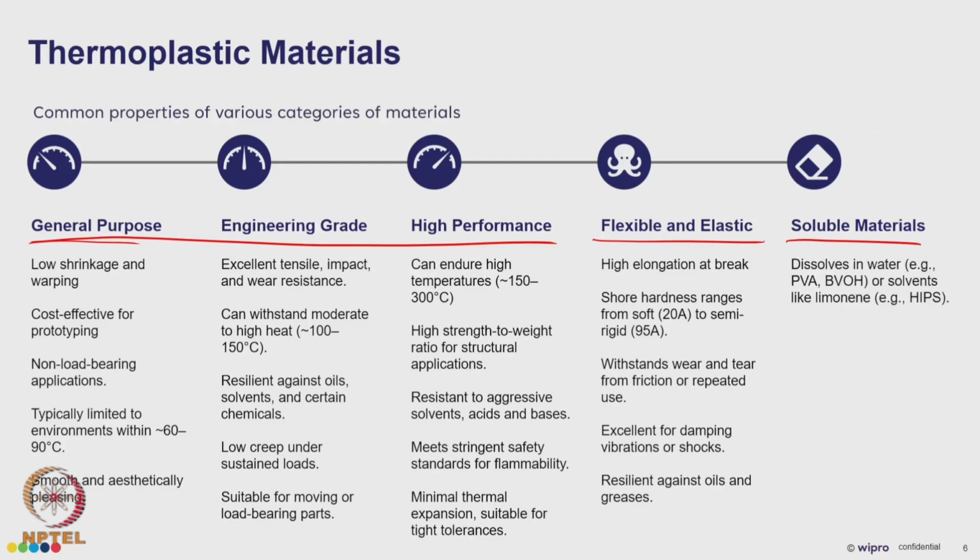And coming to the soluble material, there are certain types of soluble materials which dissolve in water, and another type which dissolves in limonene. In the case of PVA or BVOH, that is polyvinyl alcohol and butanediol vinyl alcohol copolymer, we can dissolve them in water itself, but in the case of HIPS kind of material, that needs to be dissolved in limonene.